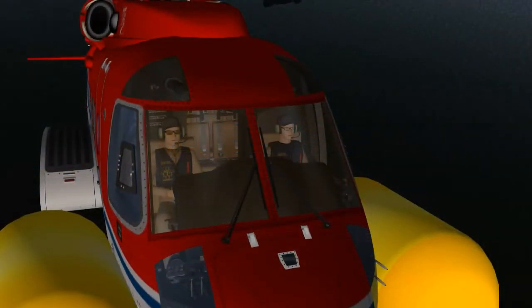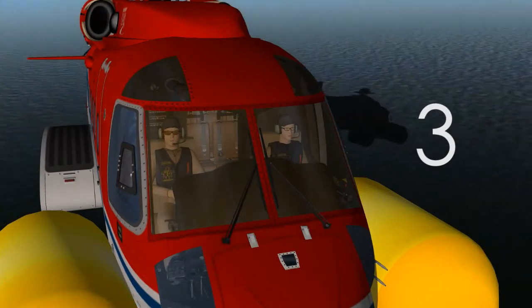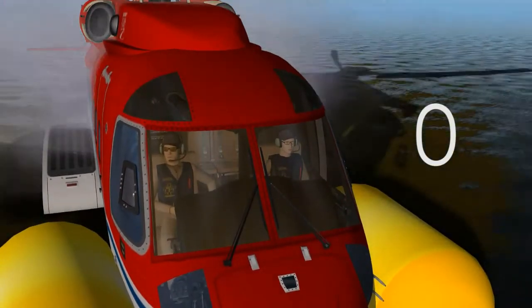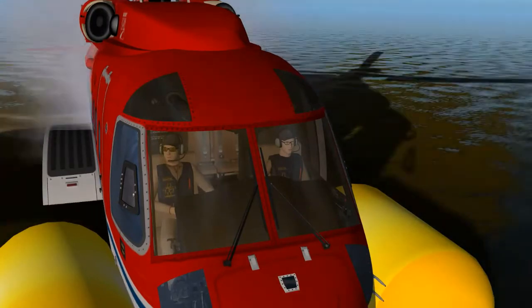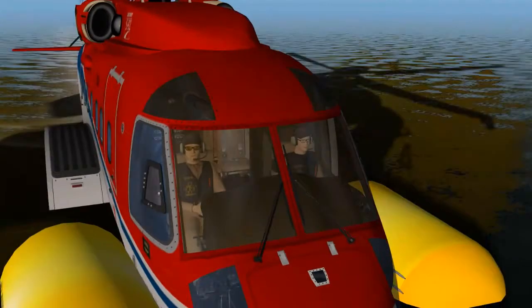Because remember, when you're flaring, you're going to hit that point where the airspeed drops off below a point that it's enough to keep the rotor spinning. So that's kind of like our stopwatch. And once that watch starts running, or that clock starts running, there's a finite amount of time in which you're going to have usable lift in your rotors.